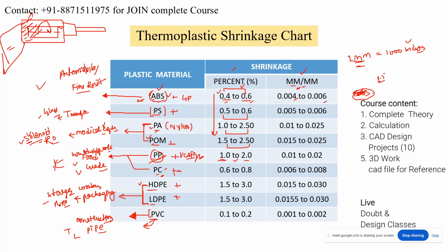We have to decide depending upon the application, and what type of shrinkage we have to provide there, symmetric or asymmetric, because it can shrink like this. It can shrink 1 to 2 percentage. Basically, we don't know for a specific material how much it can shrink after solidification, and it is also dependent upon the cooling speed, the mold temperature, or the material quality, right or wrong?